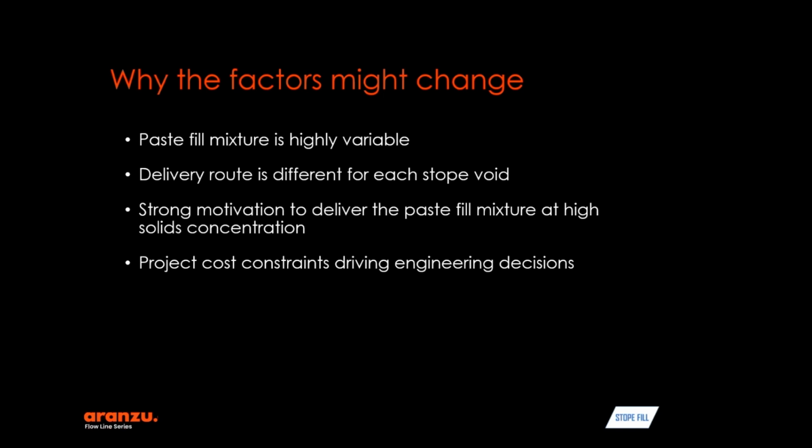Other influencing factors are due to the ore body shape; the delivery pipe route will be different for each stope void. There is also a strong motivation to deliver the paste mixture at the highest solids concentration possible.